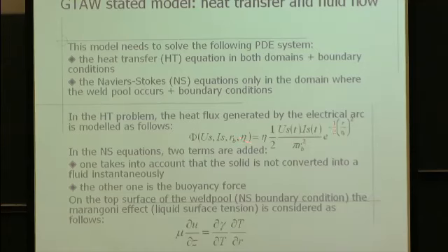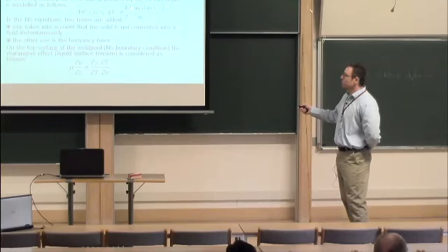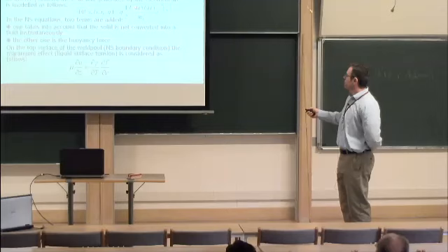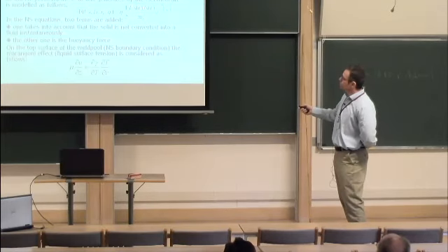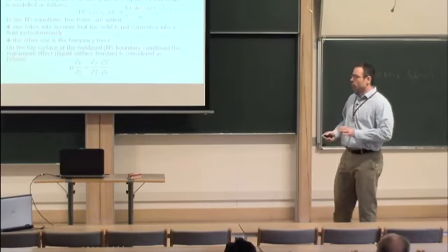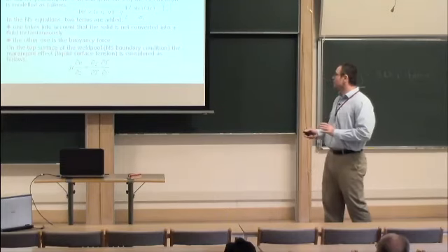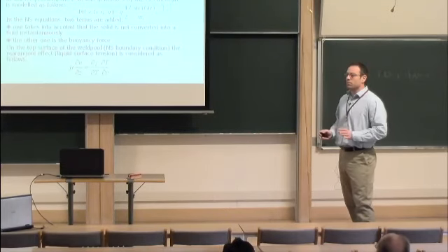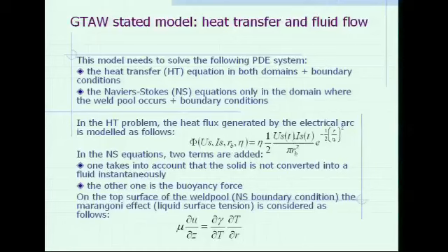The heat flux is described as follows, with this Gaussian function, where we can use the current welding set parameters, I mean the welding tension and welding intensity. We have in our facility a welding bench which we have instrumented, and we can measure the welding parameters, that means welding tension and intensity. And also we can record some images, some movies from the weld pool on the surface that will give us some information on how it behaves. And that's why you can use this data inside this formulation.